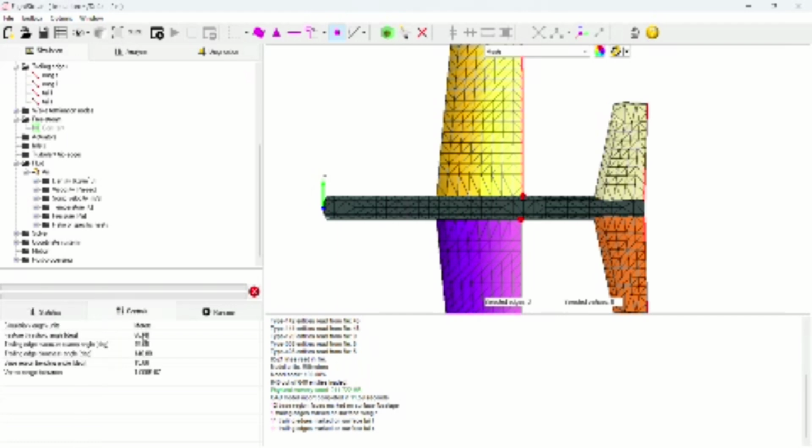Then once you are done with it, you come to the bottom menu where the controls tell you all the features of your model, and then this is a runtime analysis where we decide the angle of attack, or basically the initialization of the simulation. As we are doing it for subsonic simulation, we will keep the angle of attack as 5 and free stream velocity at 100 meter per second, reference velocity also at 100 meter per second.